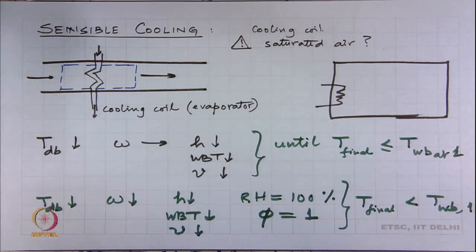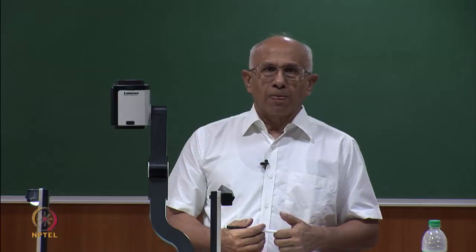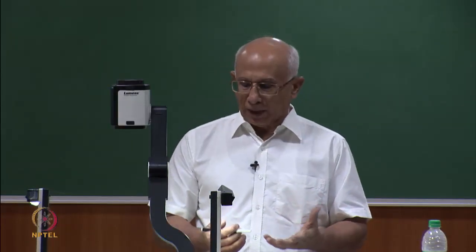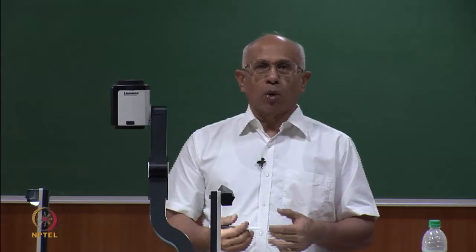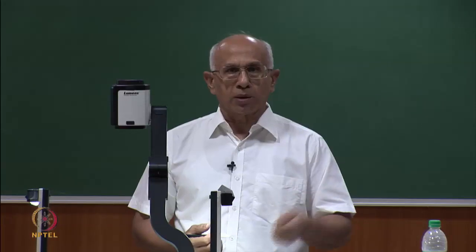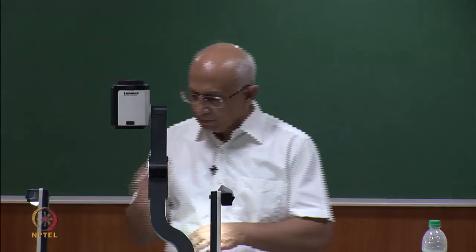And we know that when the humidity in the air increases, which means that we are now coming into the monsoons, and you are trying to cool air, firstly the air temperature does not come down too much, because all that energy is used to precipitate the water out, and one can see that from the air conditioner there is a lot of water dripping out all the time.